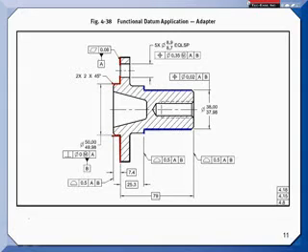Well, if you have the right thread gauges, it's not all that difficult. A company here in my town was machining transmission housings for the Chevy S10 and the Blazer. Before they would put the engine block onto the coordinate measure machine, they were using what are known as true pos pins that you screw down into the tapped holes that pick up the pitch.